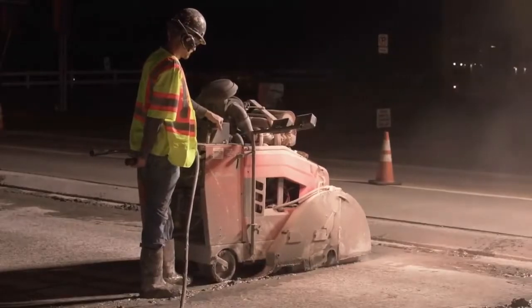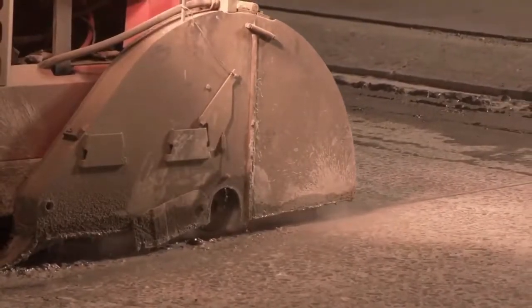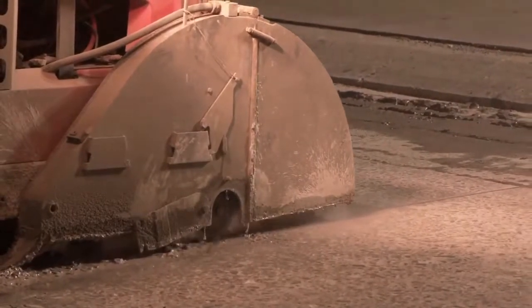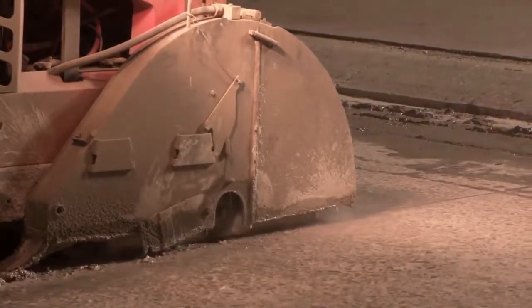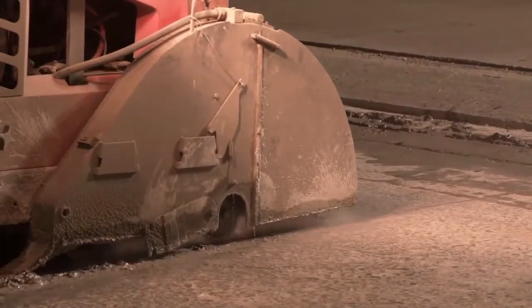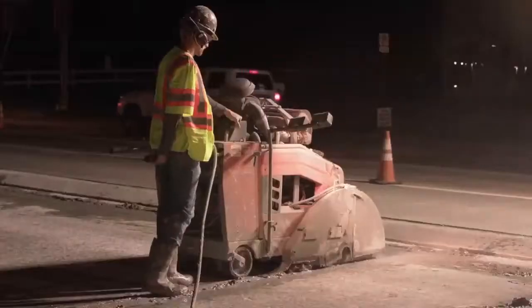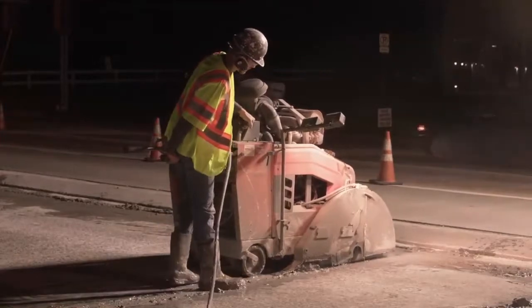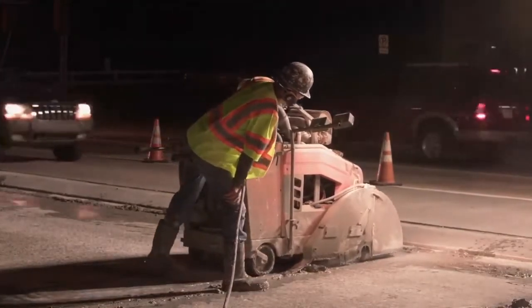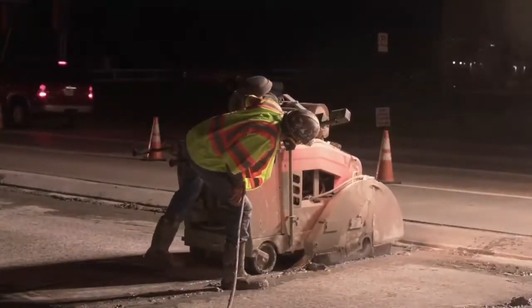Full-depth saw cuts at the patch limits will be allowed to extend transversely into the adjacent pavement up to the full depth of the pavement plus 2 inches. Additional full-depth transverse saw cuts are allowed to facilitate slab removal. However, the additional transverse saw cuts cannot extend transversely into the adjacent pavement to remain in place.